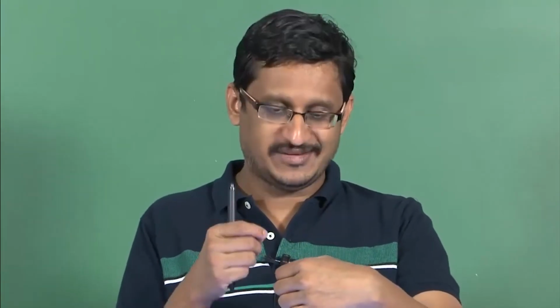So, I am assuming that this is a direct band gap material. It makes our life a little simpler, the efficiencies are better, and things are much simpler to understand without the involvement of any phonon, which would otherwise be the case for an indirect band gap semiconductor. So, in this direct band gap semiconductor, if I forward bias the photodetector, then I would have created an inversion, or essentially created a large number of electrons in the conduction band, because I am forward biasing this, and then I have empty states in the valence band.